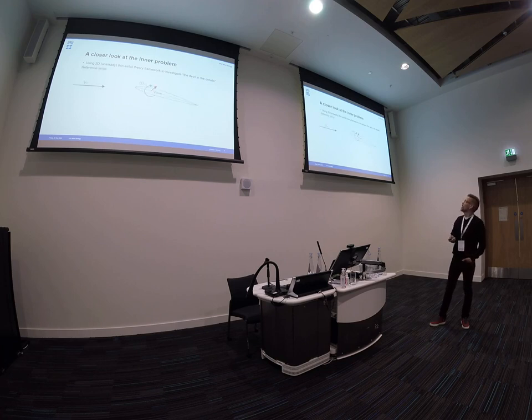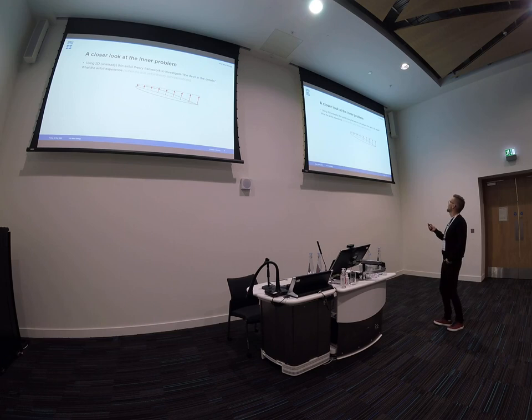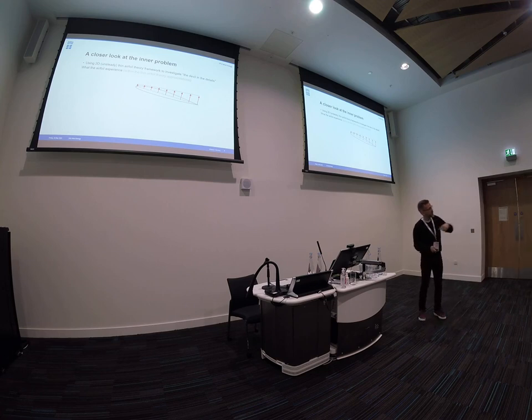How you do that thin airfoil theory, unsteady stuff, is you have a reference setup with a constant wind speed, and then you have an airfoil that moves around. It has translation and rotation. So what the airfoil feels is different velocities at different locations along the chord. This is the component perpendicular to the airfoil, and then there's also a free stream velocity, the other component of it. But along the chord it experiences different things. And the key thing here